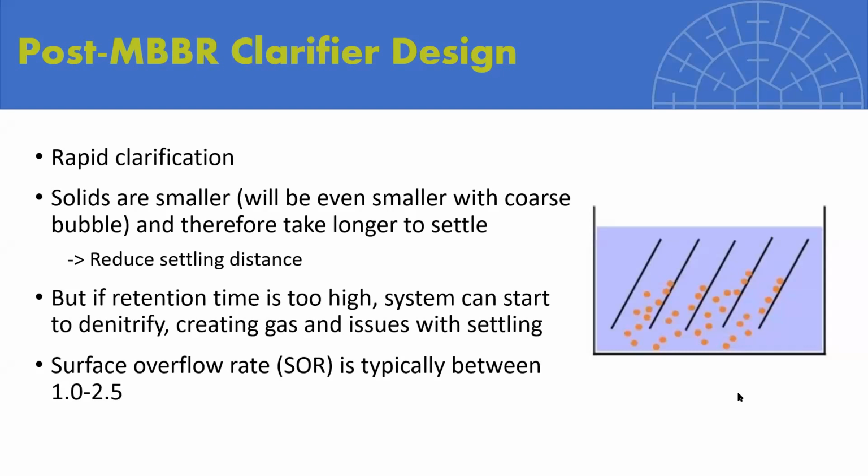If you use coarse bubble, however, you are going to have more turbulence in your MBBR system. It's going to be breaking up more of those particles, more of the biology, and so you will have even smaller particles, which is harder to settle in your clarifier.